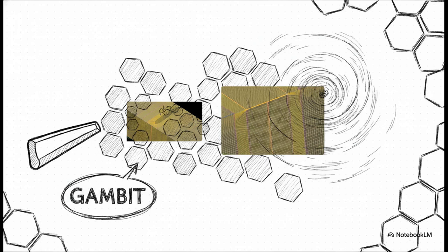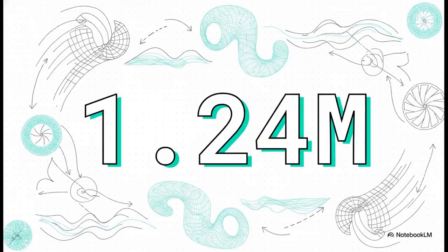Engineers often use regular hexagonal meshes here because this specific pattern acts as a super stable foundation for the incredibly heavy math they have to do, especially around the blade tips where the air gets violently turbulent. So, how many of these tiny blocks do you need? Well, engineers actually conduct a sensitivity study, comparing several different mesh configurations to find the perfect balance.